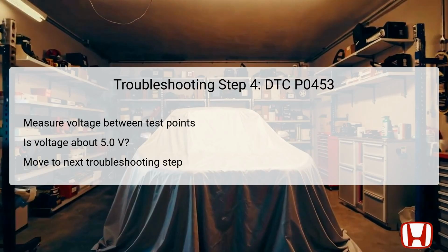However, if the measured voltage isn't near 5.0 volts, it suggests there may be an open in the circuit, requiring further investigation into wiring continuity and possible repairs.